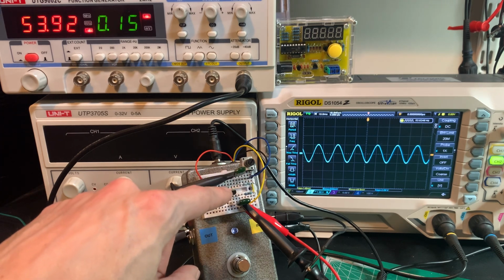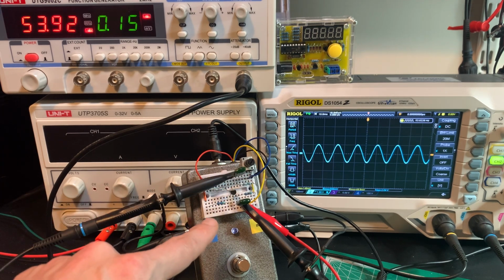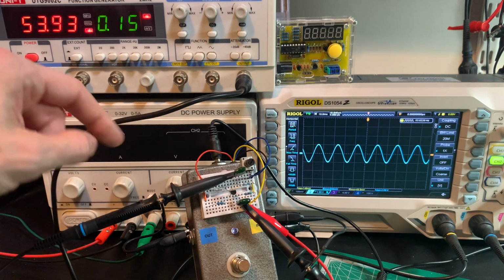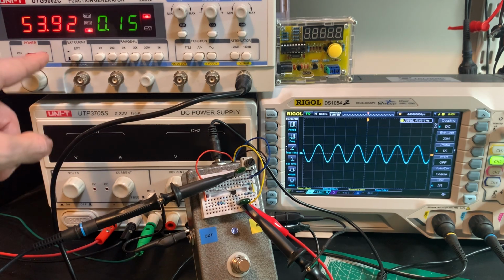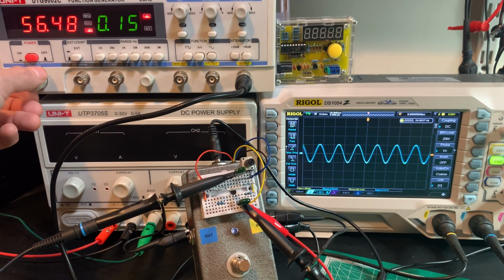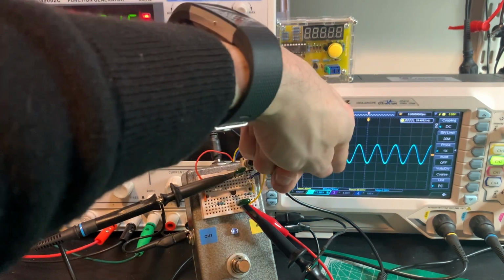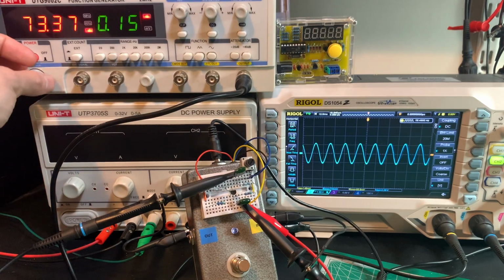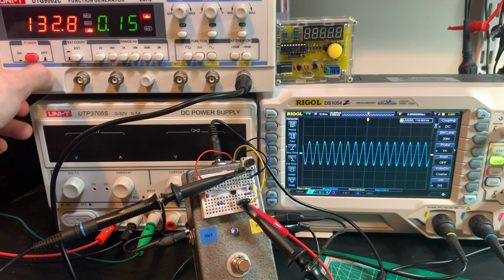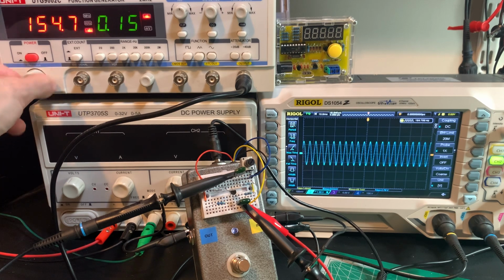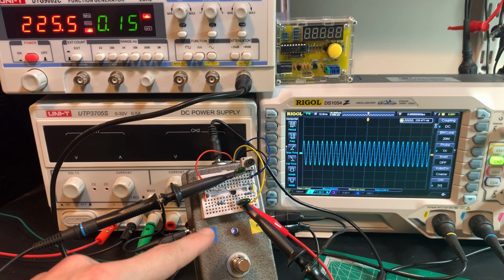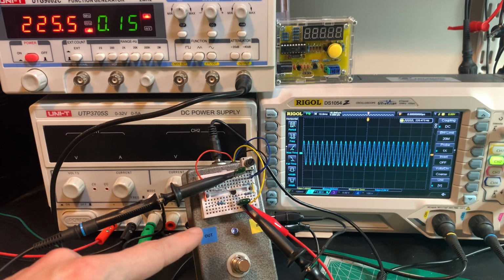And obviously we've got a slightly different beta of our transistor as well, which is going to affect other things in the circuit. But again, it's close enough. Now, you can see, hopefully, as I increase the frequency, that the peak-to-peak amplitude and the RMS of the waveform gets higher. You should see it's growing, basically, on the screen. So that shows nicely that it's a high-pass filter.